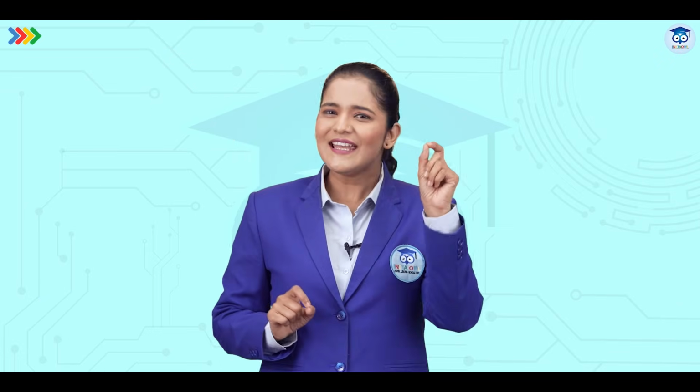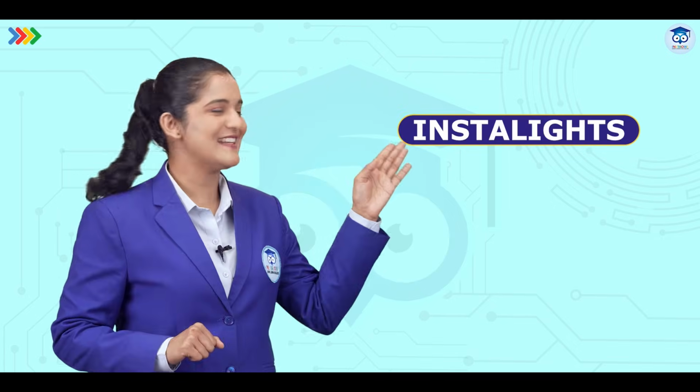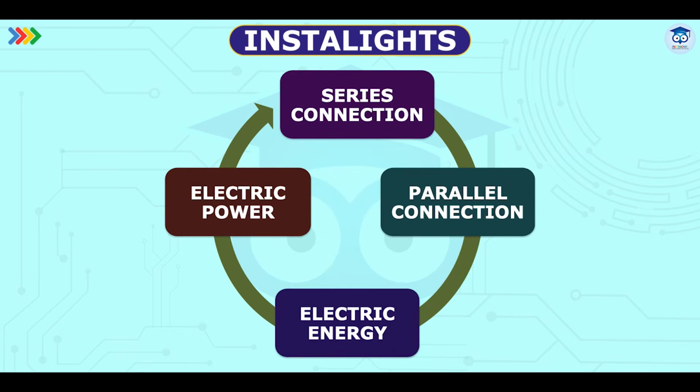And now, it's time to recap what we have learned in this video using our Instalights. We started with series connection, where resistors are connected end to end and the total resistance is the sum of individual resistances. Then we moved on to parallel connection, where resistors are connected across the same 2 points and the total resistance is reduced.